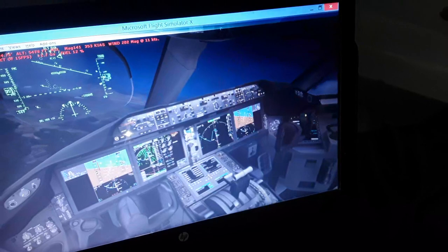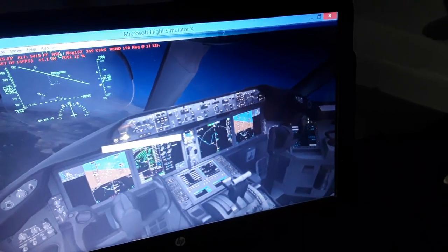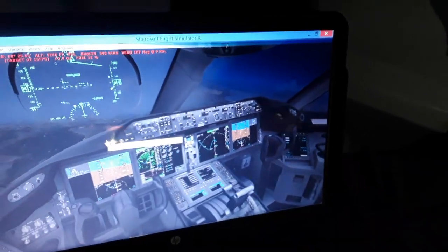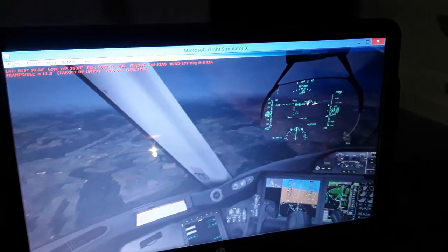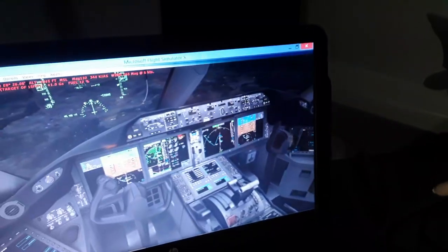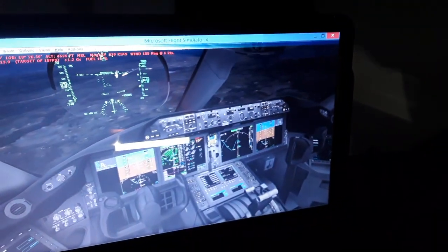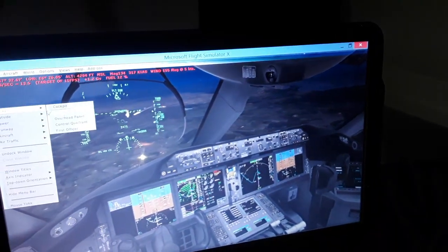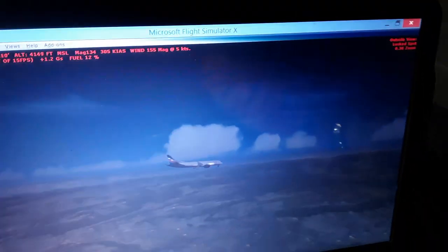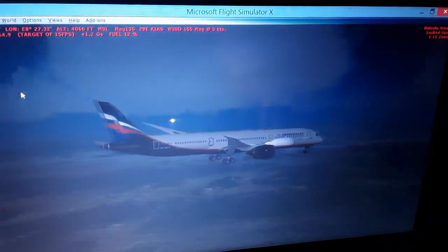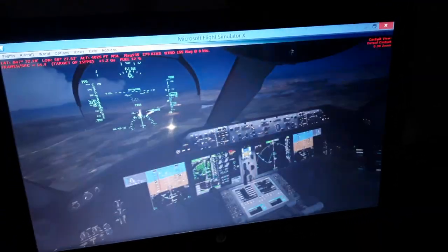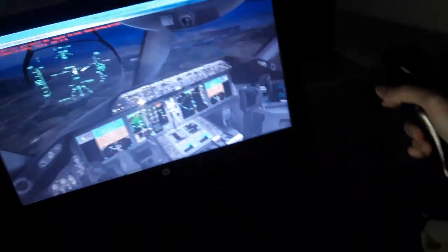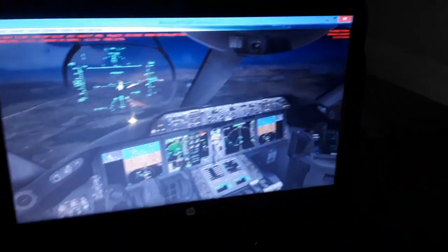Use a little bit of left rudder and right rudder over here for the side wind. Also landing gear down. And also flaps. We're gonna use some flaps for approach and landing, as you can see. Also the landing view of the airplane, the Boeing 787. So we have 1 more minute for approach and landing. Very easy. We're gonna make a manual approach.